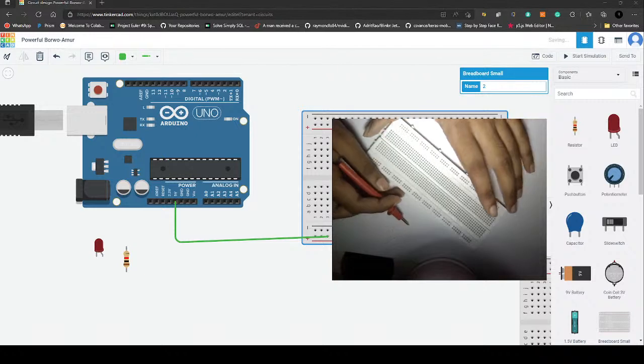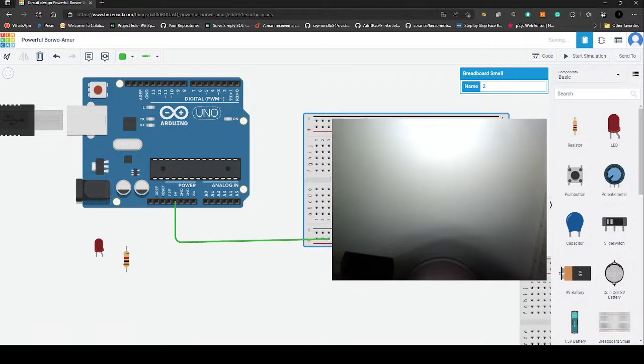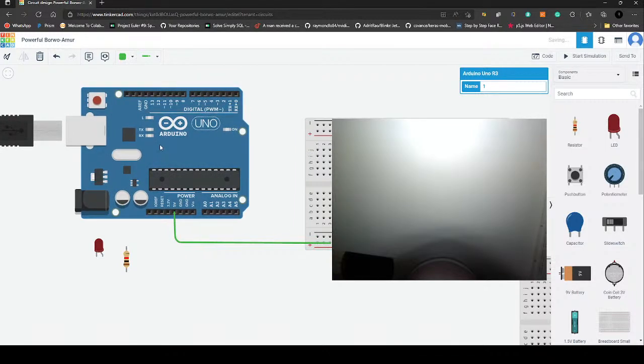So whenever you start making a project by yourself in physical mode, always pay attention to what wires you are connecting, because if VCC and ground touch, the board may short circuit, and this will be just a waste.